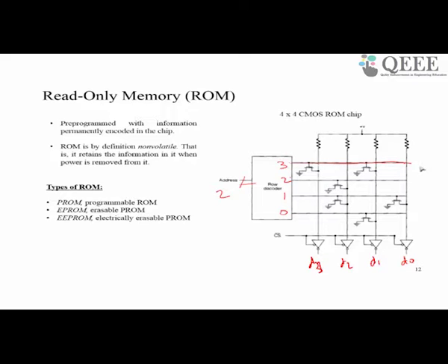When the line 3 is selected, the gates of these transistors are asserted, which effectively allows a conducting path from this plus V through this resistor to ground, and current flows and the voltage gets dropped here, and this will be close to 0. Whereas for these points there is no connection, so this will be close to 1. Again at this point it will be close to 0, and here there is nothing, so it will be 1. So whenever there is a cross point, the corresponding line will be 0, otherwise it is 1.